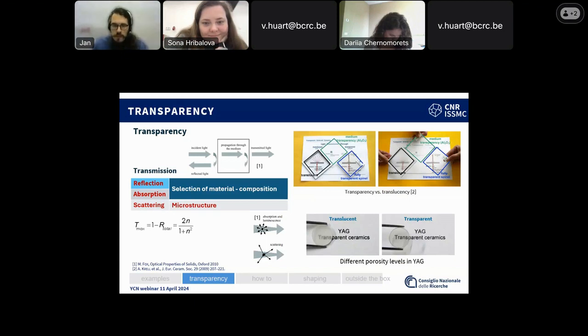Okay, another possibility that's more for the thin layers or for 2D structures or 1D structures is tape casting, where you produce these thin sheets and you can stack them, thermocompress them at some 100 degrees into these layered parts, and after some debinding, you can sinter them to transparency. And again, here you can play with the composition of the different layers and prepare even graded structures.